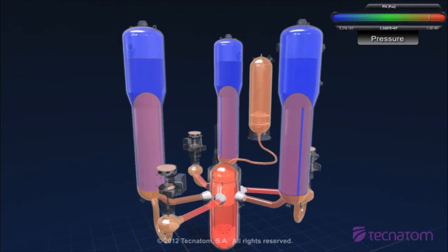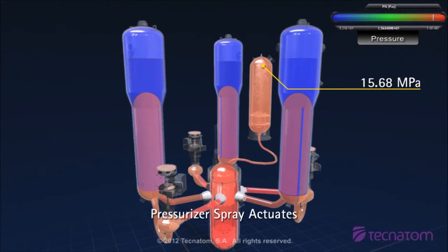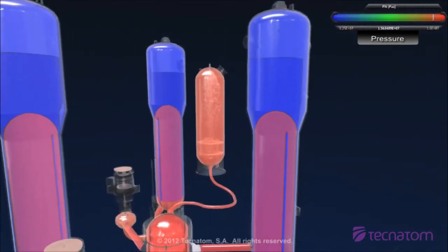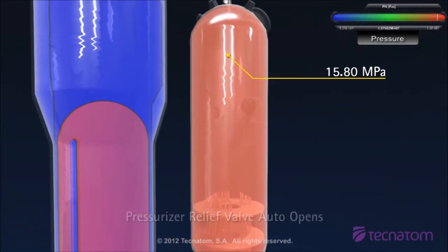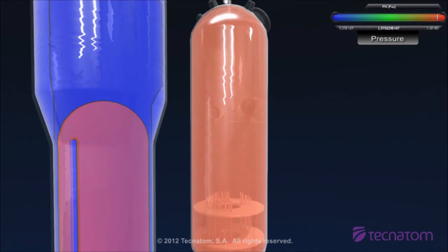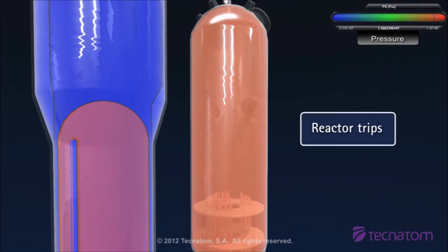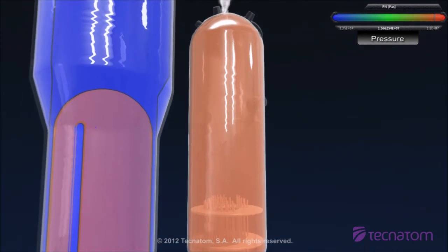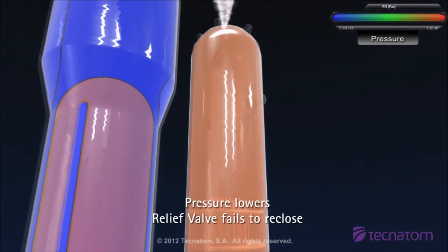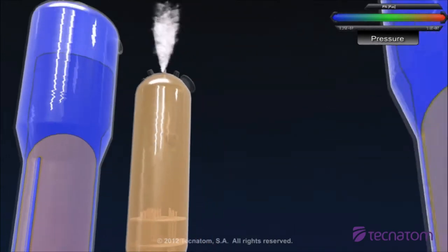Automatic pressure control actuates and spray valves open to try to maintain pressure. However, pressurizer relief valve set point is reached and valve opens to protect the integrity of the primary. When valve opens, pressure increases at a slower rate until reactor automatically trips. Protection system actuates to automatically shut down the reactor. After the trip, pressure and temperature decrease rapidly, but pressurizer relief valve fails to reclose.